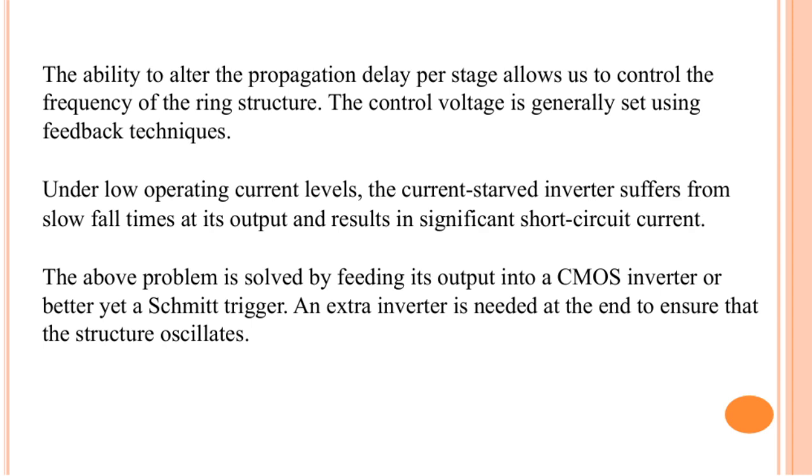To address this, we feed the output into a CMOS inverter, or even better, a Schmitt trigger. This approach improves signal integrity and speed. Additionally, we include an extra inverter at the end to ensure the oscillator continues to function properly, maintaining stable oscillations.